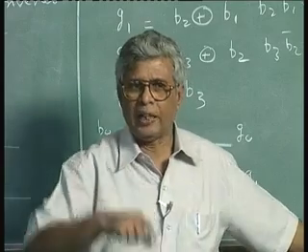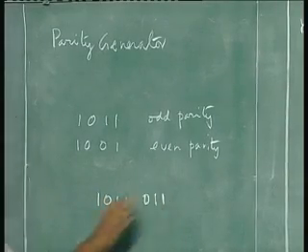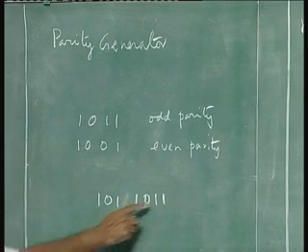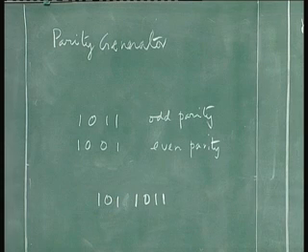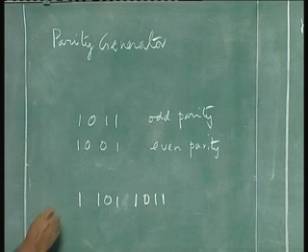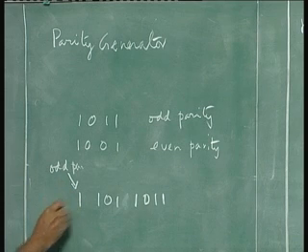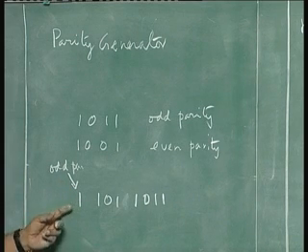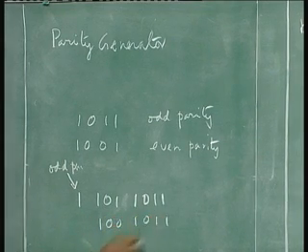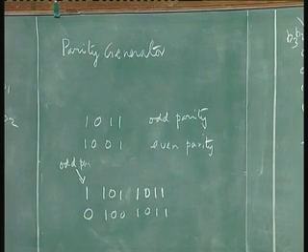So they will also put the parity along with that. For example, take an ASCII code, a 7-bit code, and let us say this is my code. Now I count my ones: 1 2 3 4 5. For an odd parity, I can put a 0 or 1 here, depending; I put a 1 here to say it is an odd parity. So I add an extra bit to say that I have an odd number of ones. On the other hand, if the number of ones is even, I will put a 0. So I deliberately add a parity bit.